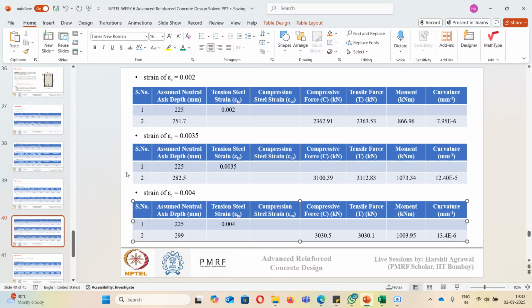So similar to the case that we saw without compression steel, you can see once the concrete passes the ultimate strain value, the moment capacity starts to drop, because here concrete crushing is still dictating the capacity of the member, and that is the limitation of an over reinforced section. Okay, there will be a sudden drop in the capacity of the member because of its brittle nature, because concrete is governing the design.